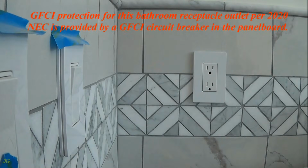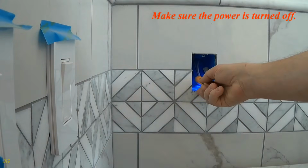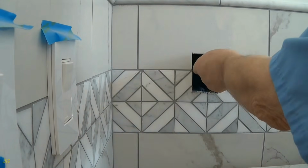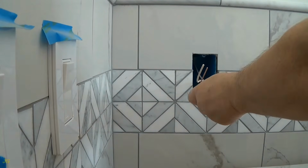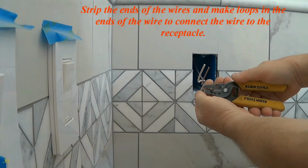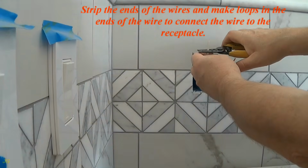GFCI protection for this bathroom receptacle outlet per 2020 NEC is provided by a GFCI circuit breaker in the panel board. Make sure the power is turned off. Strip the ends of the wires and make loops in the ends of the wire to connect the wire to the receptacle.